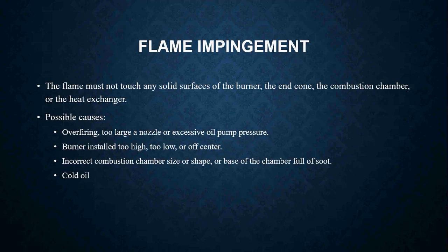Look at your manufacturer specifications for that burner. If it's supposed to be at 100 psi, set it for 100 psi. If it's set for 150 psi, you set it for 150 psi. Whatever those specifications are, you have to follow them. Burners installed too high, too low, or off-center. Well, it's just a screwed up design to begin with. Whoever put it in went on some website and did their own research and put it in, or you had some incompetent mechanic that came in and put it in, didn't know exactly what they were doing, and screwed up the design to begin with.